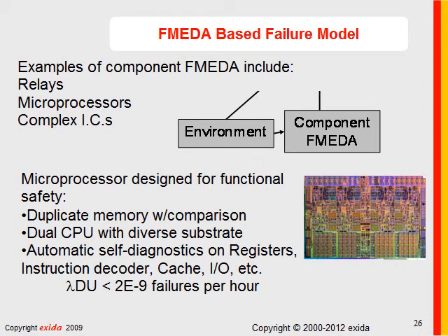You've got the coil, different coil types with different insulation, different kinds of magnetic coupling with failure modes of residual magnetism, contacts, springs. A detailed study of the components of the relay results in failure rates and failure mode for the relay component, which then goes into the component database, which then is used for an FMEDA for a product level, like a gas detector with a relay output.